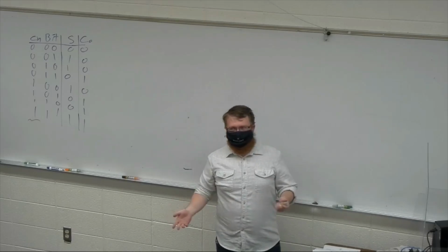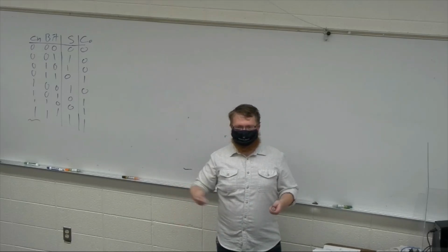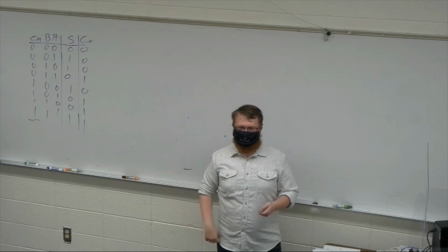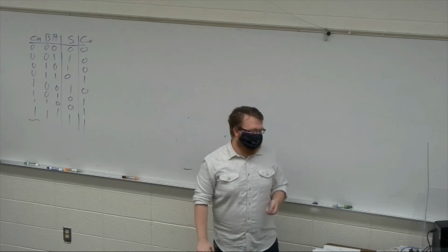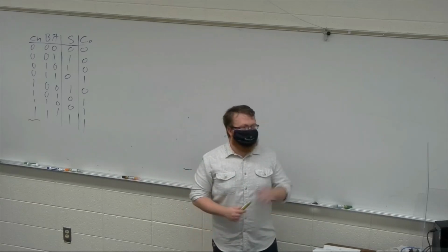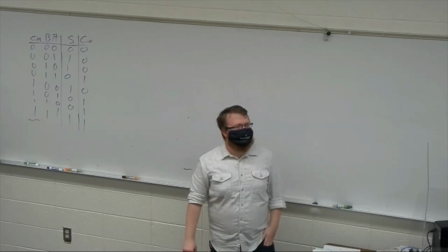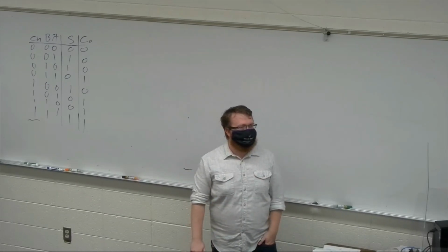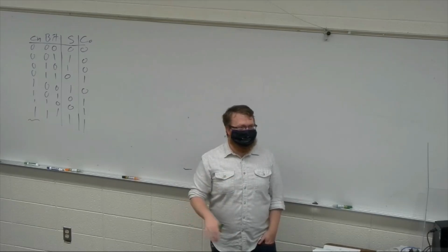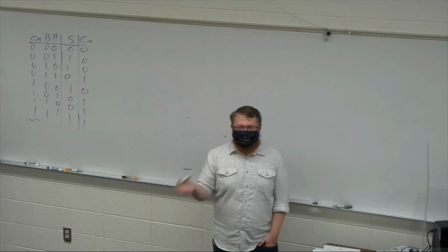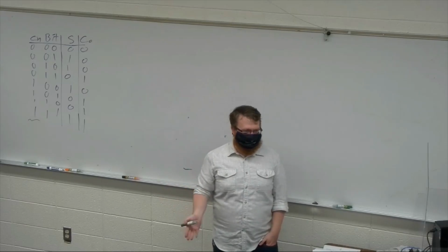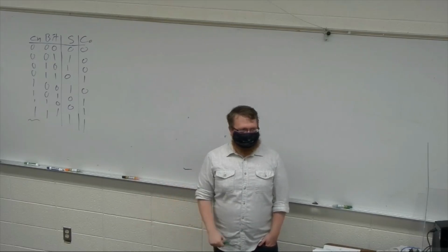The other way is you can get a really high speed oscilloscope and just start throwing a switch and watch it bounce. That's how I do it almost every time. I don't know, it probably has a real name. I just say click count sample because that's how I do it, and it's super easy.